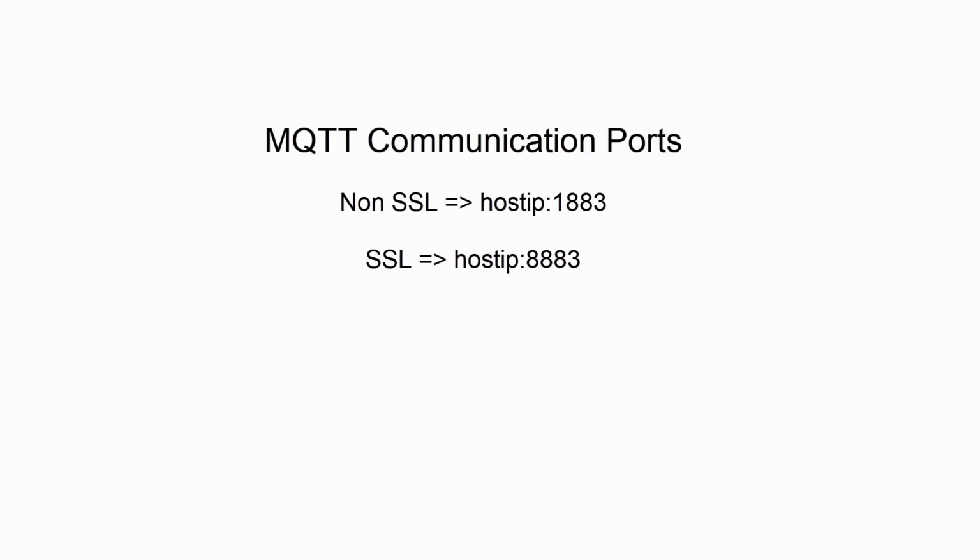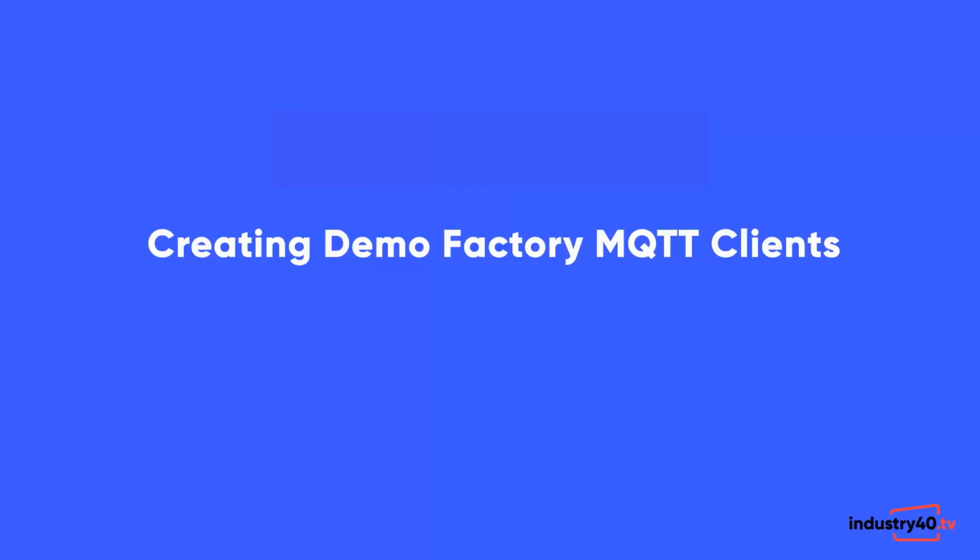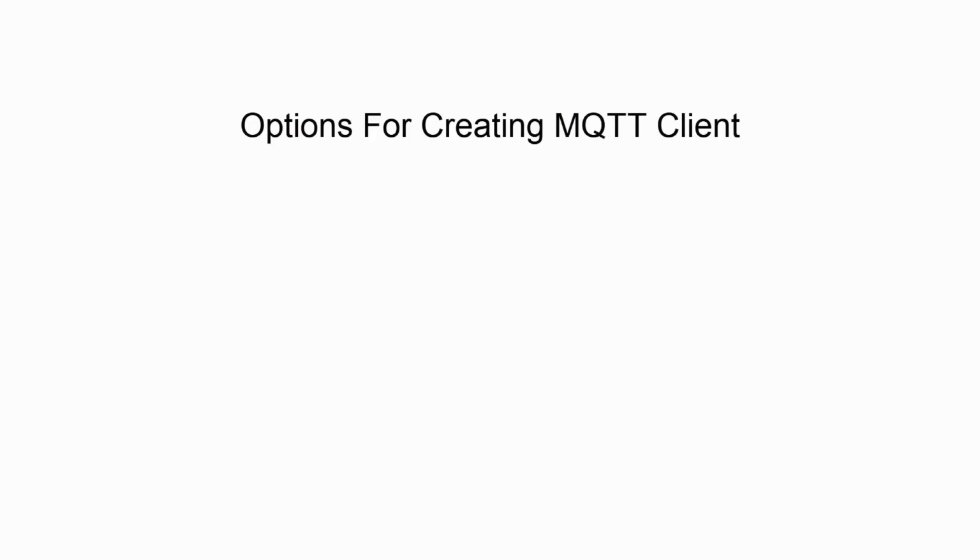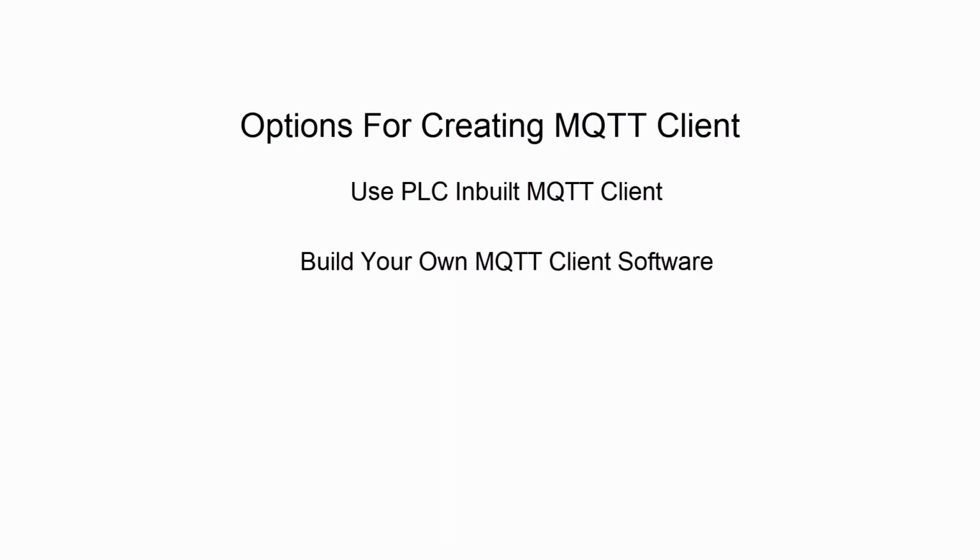So now that our broker is up and running, we can go ahead and create MQTT clients and test if it is working. I'm going to show you how to make our Opto22 device a client to our MQTT broker using Node-RED. Now, I have to mention that Node-RED is not the only solution that can give your control system MQTT client capabilities. Some PLCs are MQTT enabled by default, or you can use a C# or Java MQTT client running on a PC and communicating to your PLC.